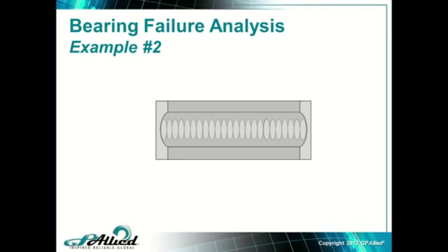And it's not subsurface fatigue. These are actually indentations. And for those of you who've never seen this, this is actually called electrical fluting. This is a little bit different than a variable frequency drive motor that's grounding through the bearing. That's not what this is. What this is, the motor has an electrical problem, and it's actually trying to beat its bearings out because it's vibrating at some electrical frequency, which is 2 times line frequency.